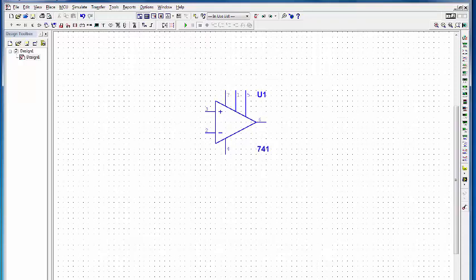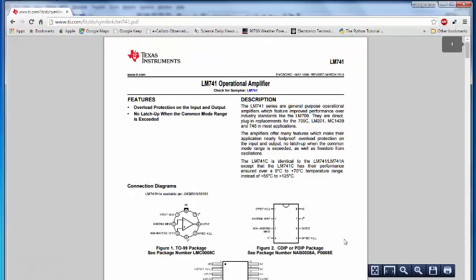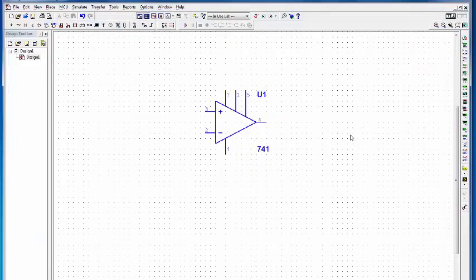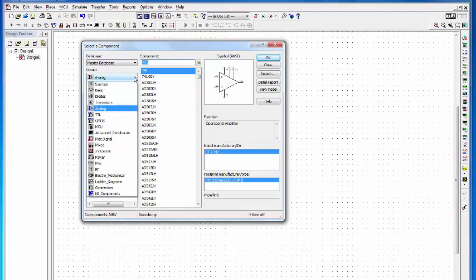then you have to get concerned about the offset null. So let's check back at our data sheet for a moment and see where the plus voltage needs to go and the minus voltage, which I should have noted and I didn't. Open that data sheet back up. The plus voltage is pin 7 and the minus voltage goes to pin 4. So we need to remember that. The plus is pin 7 and the minus voltage is pin 4. So let's power the device up first. The device will not work unless you power it up. So let's place some power for our op amp.